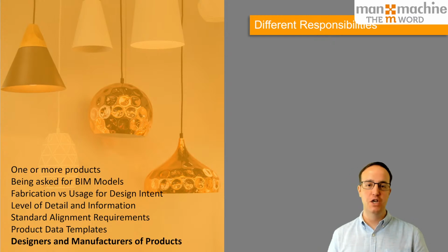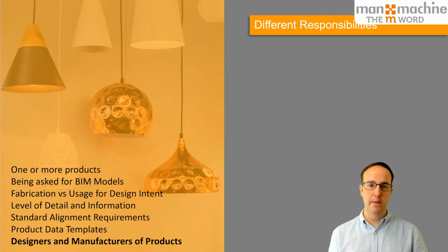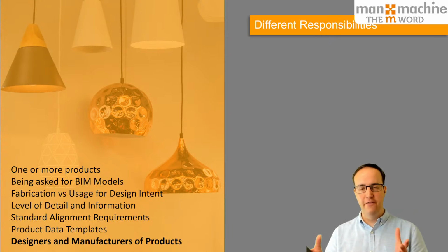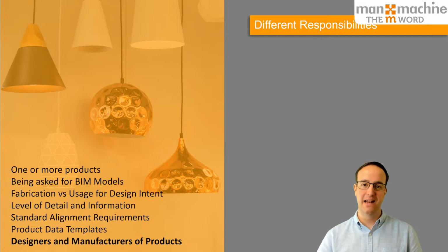So we can do a lot of simplification to get those components more friendly for the software that they'll be used within. In Inventor, you're modeling one of them. You model it to fabricate it, so it's fully detailed. If you take that HVAC unit and put it into a building, you're going to have tens, if not hundreds of those units around a building potentially, depending on the size, naturally. But with those, the more you have and the more detail, it will slow the model down. It will make the people using them not want to use them, and it will become a hindrance. So look at what you need versus maybe what someone that's placing that in a design might need. That links directly to the level of detail and the information. It's all related to the same thing.